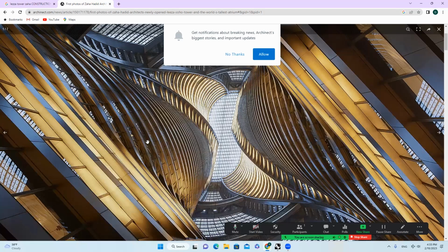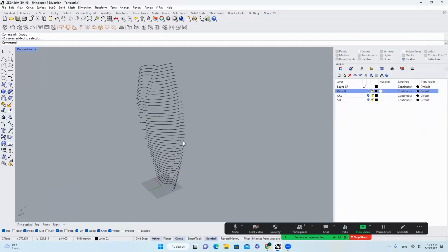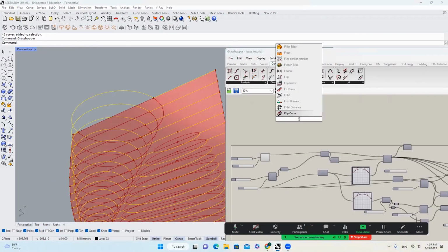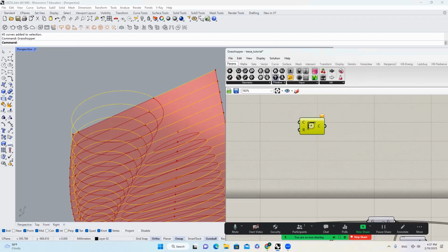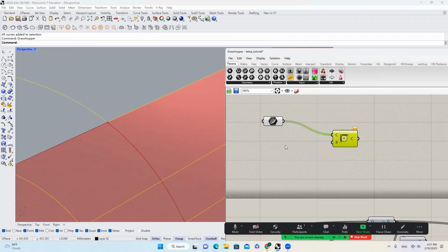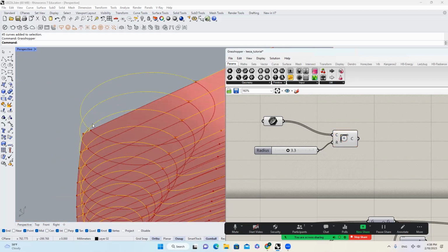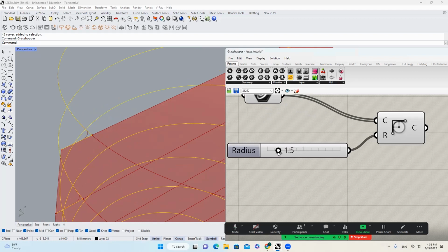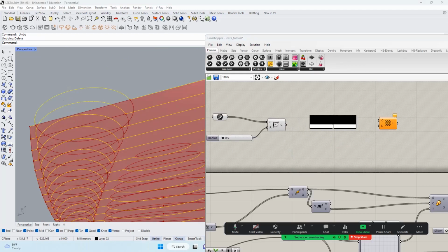Again, they have this kind of extrusion, okay, to hide the flooring and everything. So I will come over here to fillet. And then I will bring in all those curves. In the corner, I will do 3.3. See, it's way too big in some of the corners. So I'll do 0.5. The next thing I'm going to do is I'm going to move them up for 5 units.